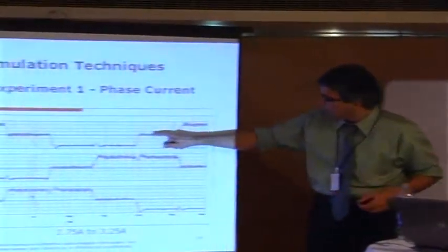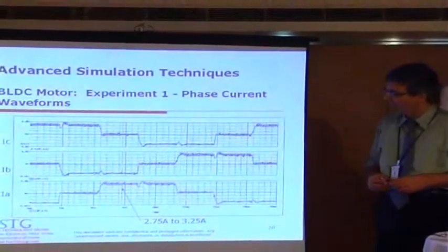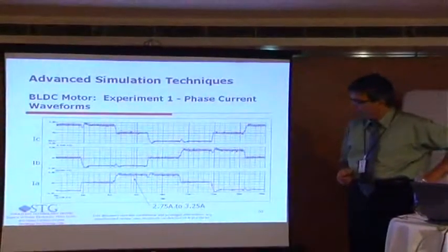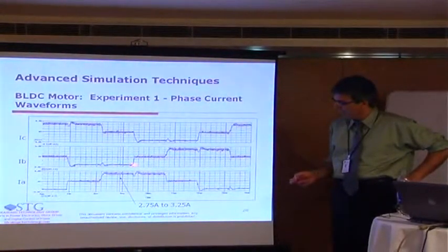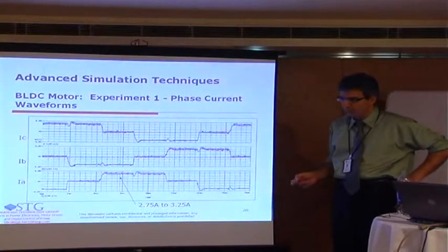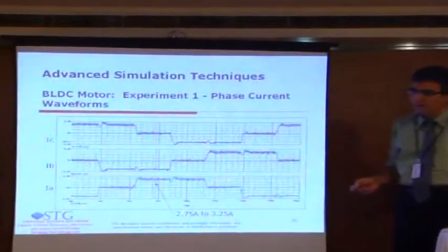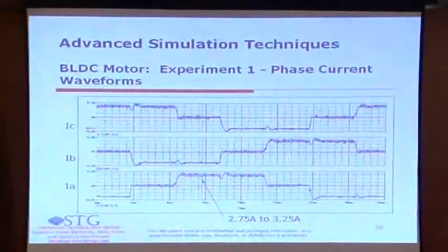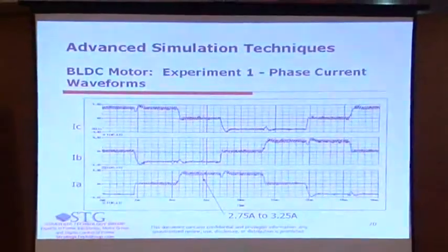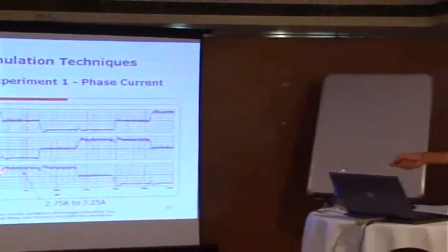You're talking about this ripple, right? Not only that, during the changeover also, the dip will again depend upon the inductance value. During the transition phase, again the dip will be controlled by the inductance value. Yes, during the transition phase also, the magnitude of the current fall, delta T, is controlled by the inductance value. That is correct.